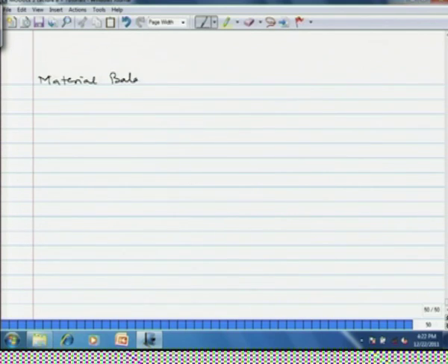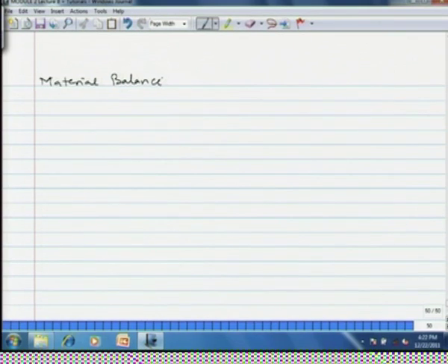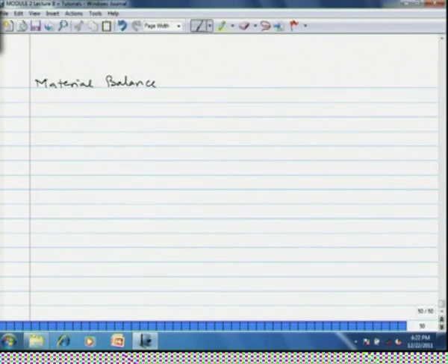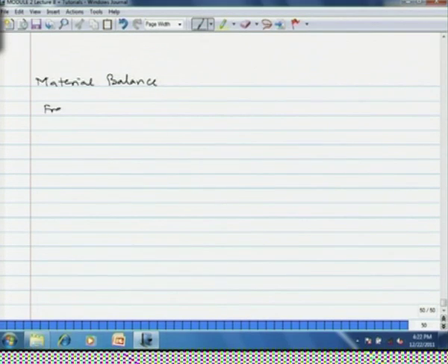Material balance. Now, the material balance I am giving in terms of the variables; we can put the numbers later. The fresh toluene feed, which we denote as FFT, will be equal to PB by S, where S is selectivity, which we have been given as 1 minus 0.0036 divided by (1 minus x) raised to 1.544.